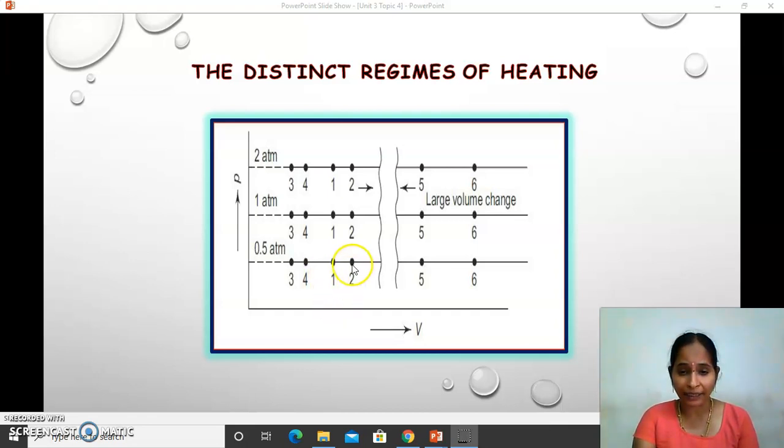And that temperature and pressure also depend on the saturation temperature or saturation pressure, which is fixed, right? Okay, so if you are conducting the experiment at 1 atmosphere, then at 100 degrees Celsius, in the state between 4 to 5, all the water would be converted to vapor.